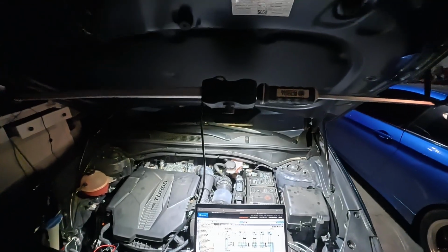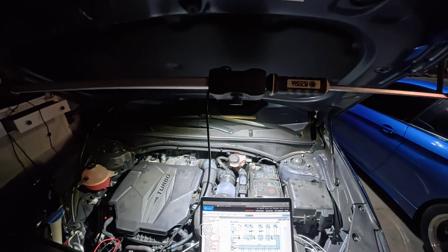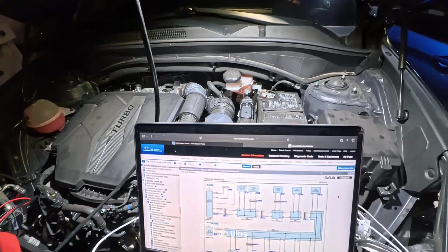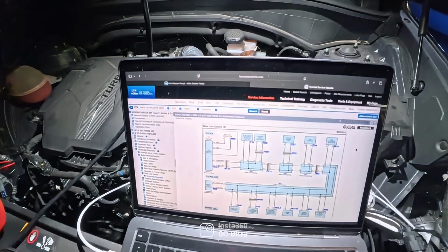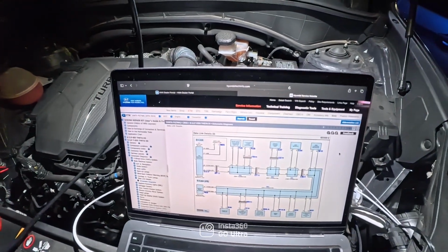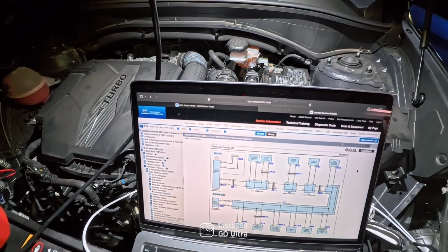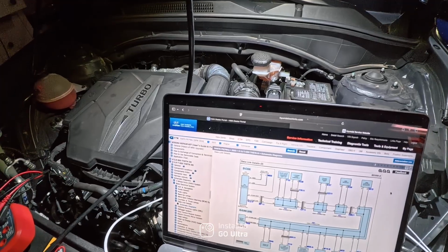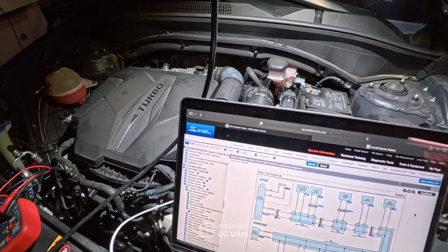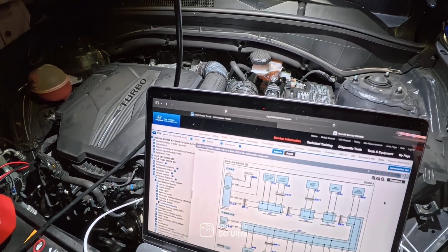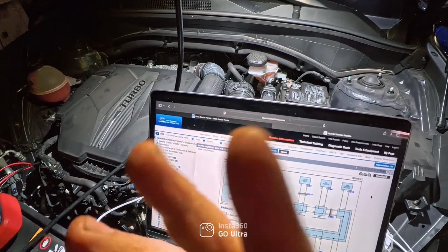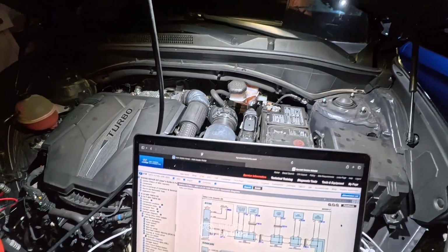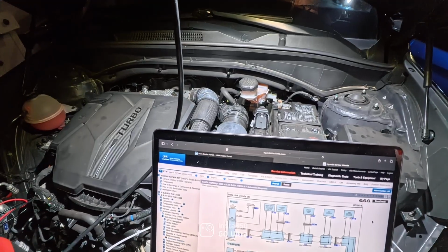However, on CAN, a lot of times, especially with Hyundai, we deal with modules that get shorted internally and bring down the CAN network. So let's take, we're back on the 22 Santa Fe, that's my wife's car. So let's say a vehicle came in with a Christmas tree on the cluster, a bunch of warning lights.